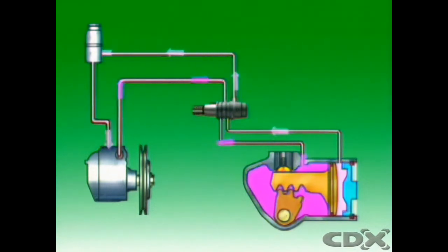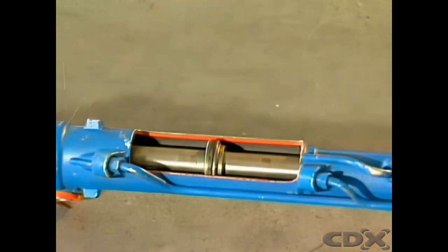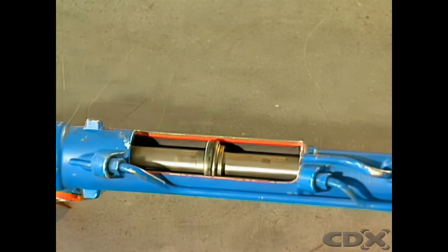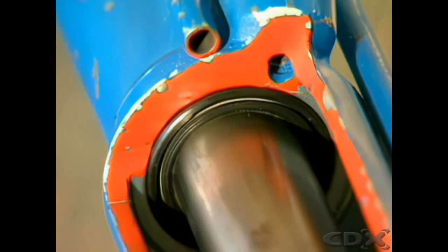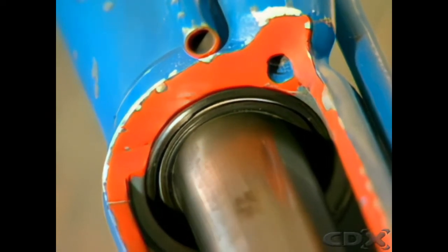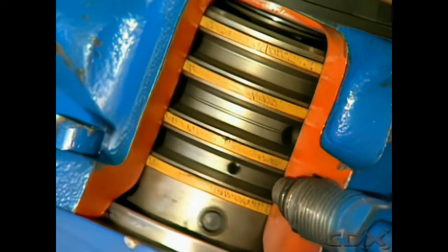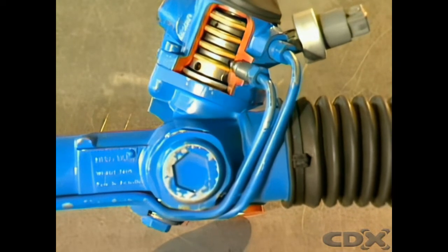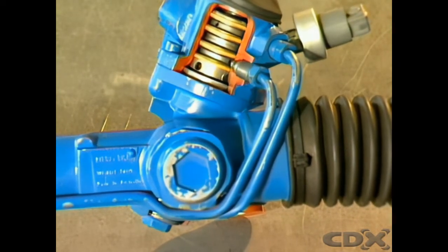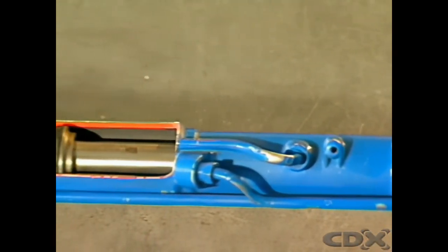Pressure applied to either side of the piston produces a force, which is transferred through the teeth to help turn the pitman shaft. In a rack and pinion steering gear, the piston is formed centrally on the steering rack, and the rack housing provides the working cylinder. Seals at each end of the cylinder isolate the power section from the rack and the helical pinion. Seals in the rotary valve section at the pinion input prevent fluid leakage there. Connecting pipes transfer fluid from the rotary valve housing to one side of the piston or the other to provide assistance, which acts directly on the rack.